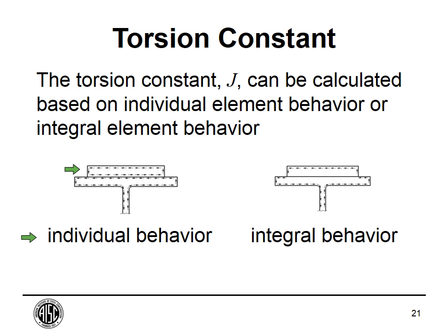Now on the other hand, let's say that we have a continuous weld between the plate and the wide flange member. So now we're going to take a look at integral behavior. And what happens is that the stresses follow the same mechanics that I was just talking about. They go around the outside of the section, but once they get up here, it goes around the combined section.